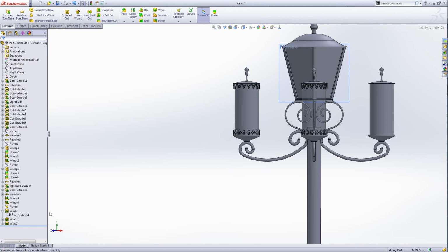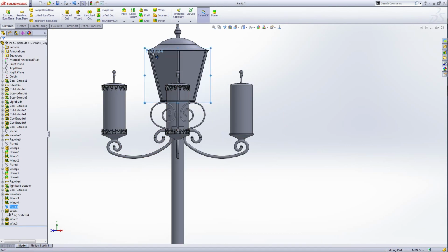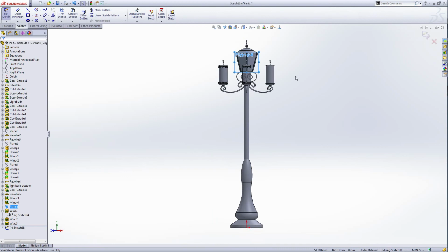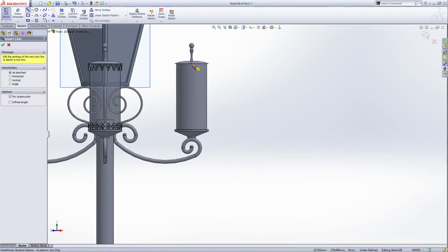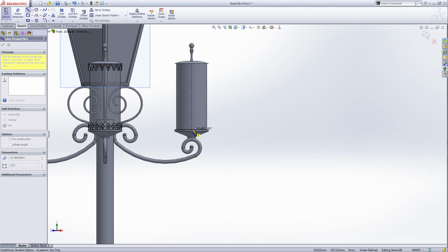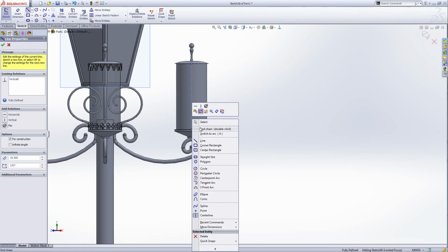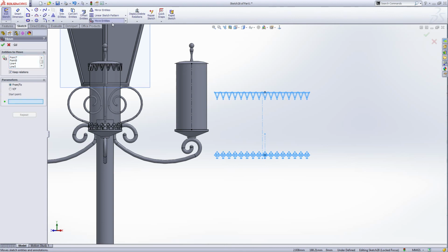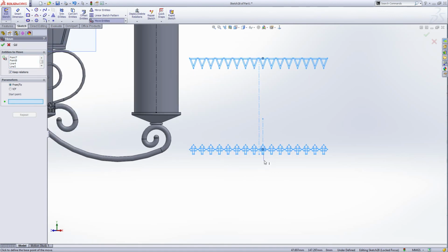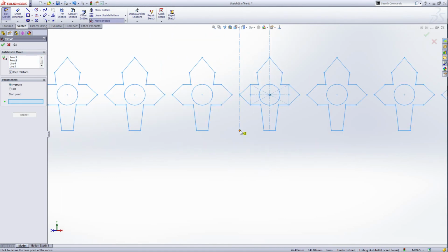Okay, now the last one. So on plane 4, wrap feature. Okay. Use the center line, connecting the two middle points of the upper and the bottom edges, and then Control V, and then move the entity. Now zoom in. We want to start from this point, so click this point.